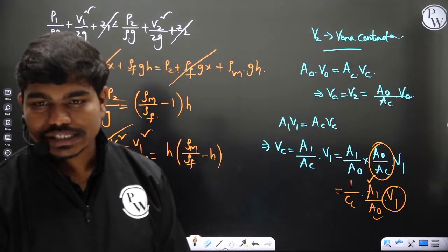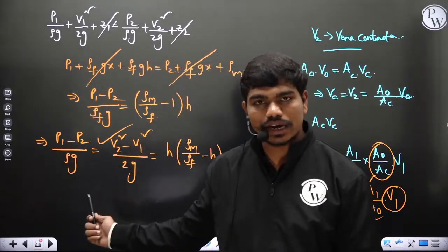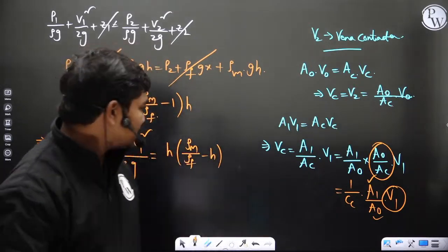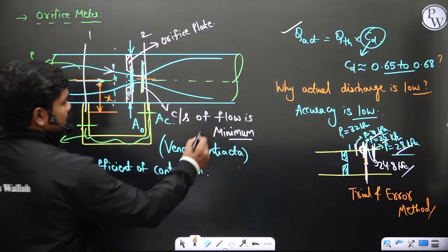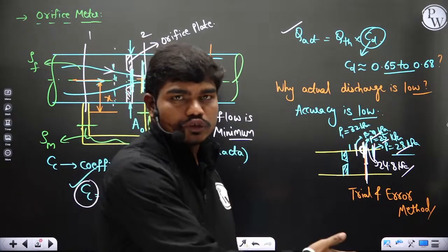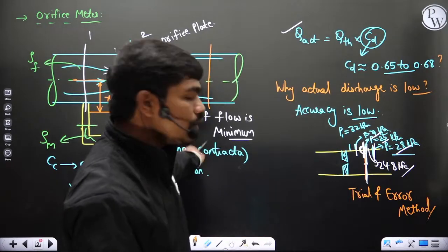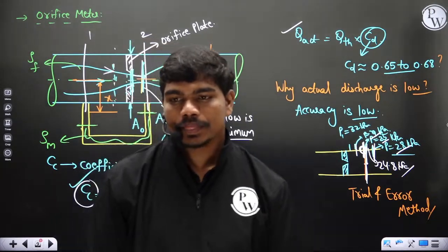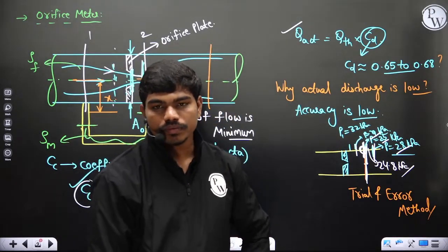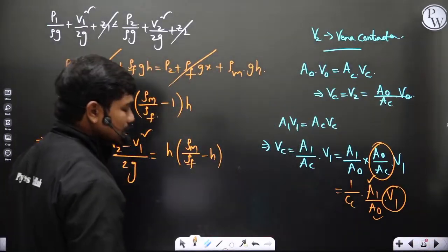Okay, so at the vena contracta the flow will be uniform, we assume that. Actually it's not uniform, because of the effects of the nozzle and losses, but we assume it's uniform throughout. In the actual case, at every location, even at this cross section, the flow is not uniform, because there is viscosity, and when we solve Navier-Stokes we'll see we have a parabolic velocity profile. But here, whenever we write, we are talking about average velocity, discharge by area average. Clear to all of you? Okay, so this is what you get in this case. Just a bit of manipulation can give you the result.